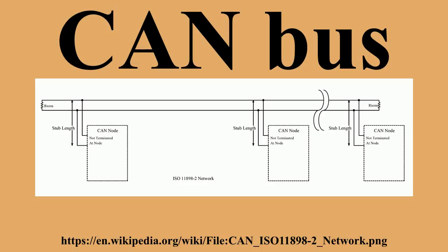Physical layer. CAN bus originally specified the link layer protocol with only abstract requirements for the physical layer, e.g., asserting the use of a medium with multiple access at the bit level through the use of dominant and recessive states. The electrical aspects of the physical layer were specified in ISO 11898-2/2003, which is now widely accepted. However, the mechanical aspects of the physical layer have yet to be formally specified.